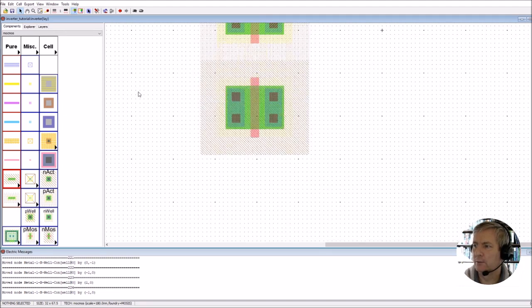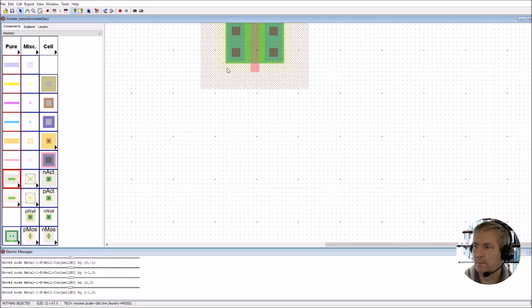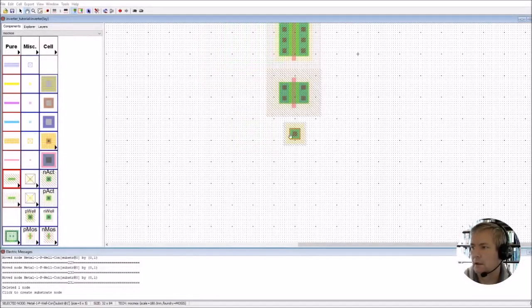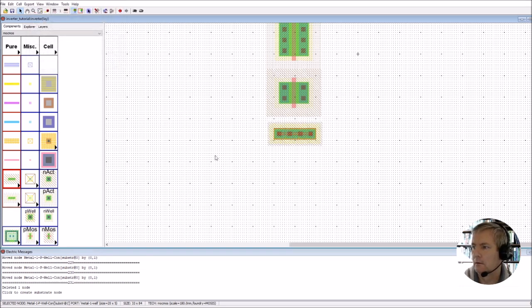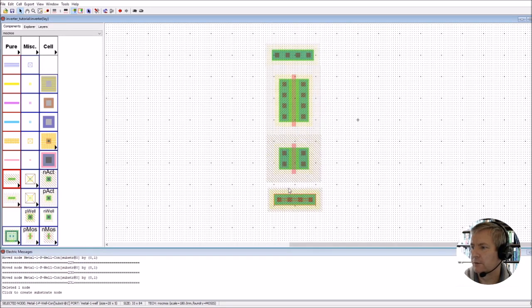Now in the bottom here we said we've got an NMOS device, so it's going to be a P well, so we're going to have access here to the P well, and that's going to be going to ground. And again we'll make this P well 20. Okay, so again we need to connect this one, so make sure that this well here connects to that well. So we just shift it up and you'll see at that point there it's now connected.